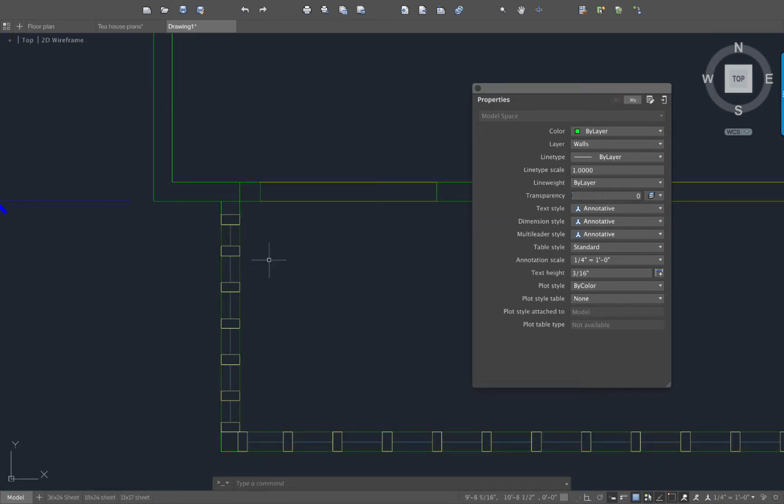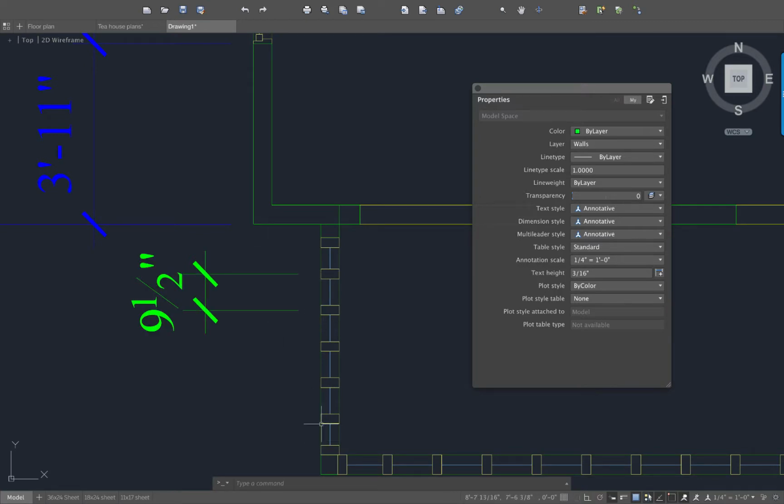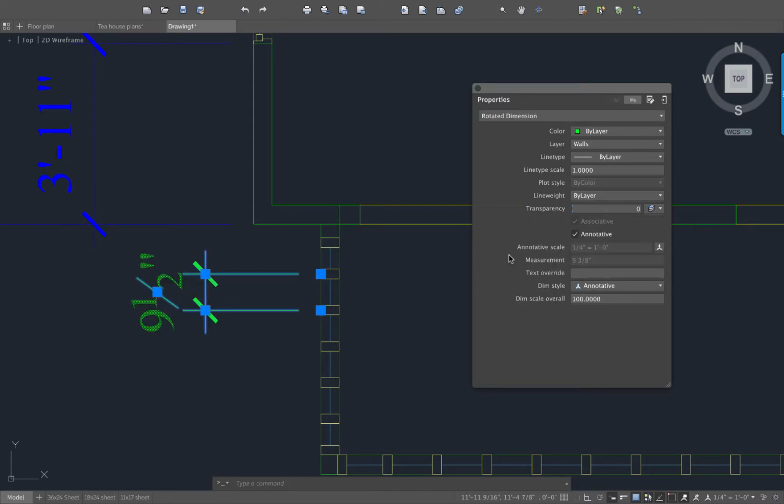Another thing that you typically will do with linear dimensions, I'm just going to put in a dimension between these windows. And this window spacing is pretty typical on this side of the building. So you could select the text and type in 9 1/2 inches, TYP, which stands for typical. Okay.